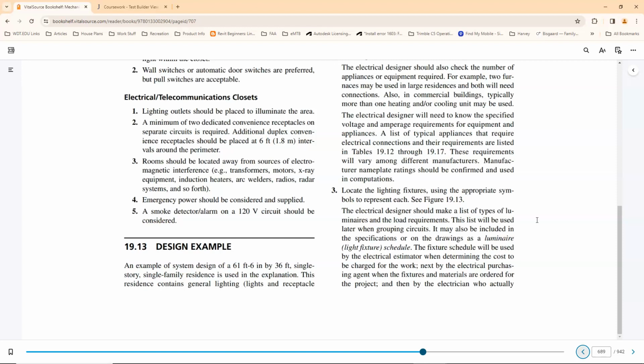So we're able to put quite a few more on a circuit. For example, a 100-watt incandescent light bulb only requires about 15 watts in an LED bulb. As you can tell, that upends the whole circuit design in terms of the lighting circuits, because we can really run a lot of lights off of a single circuit.